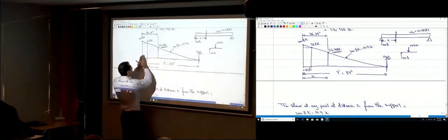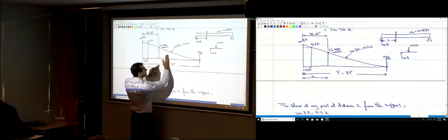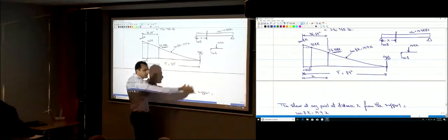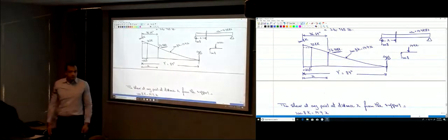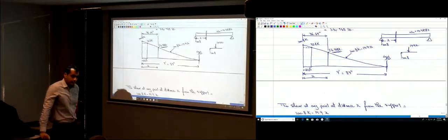Exactly, yes. So you're going to put 5 inches more here, okay? And then 11 inches spacing is going to be somewhere over here. At that point, you can use 11 inches spacing. Okay? Now, if we choose a distance that doesn't fall within the first half, just use lower spacing.